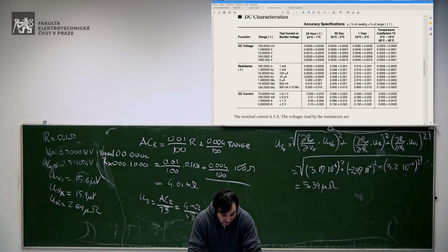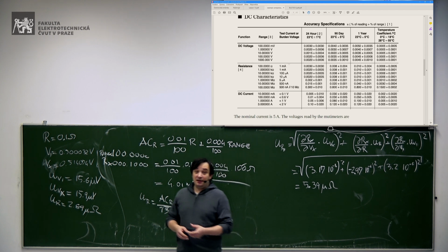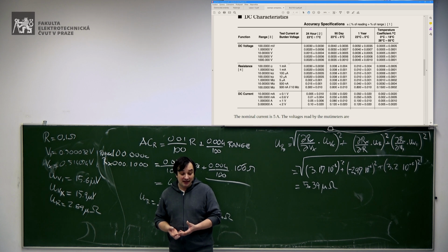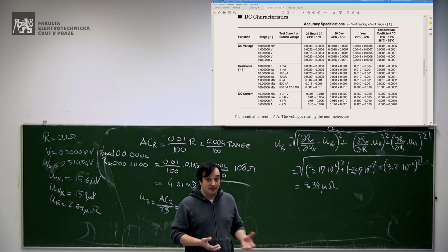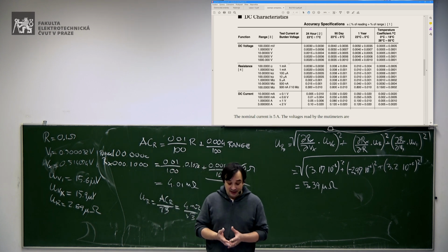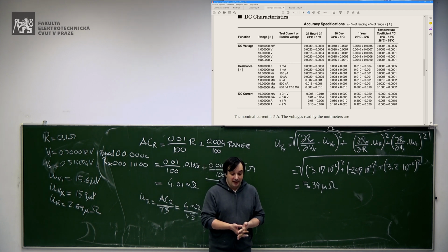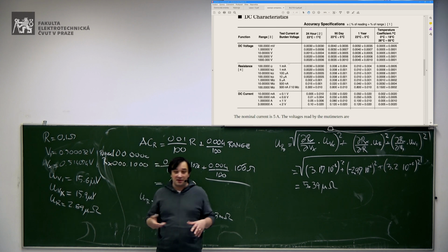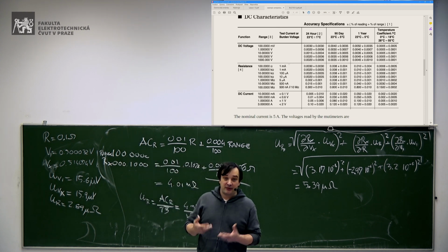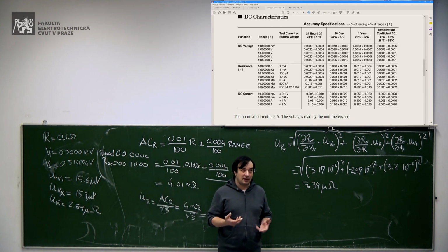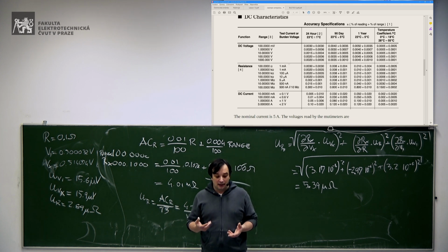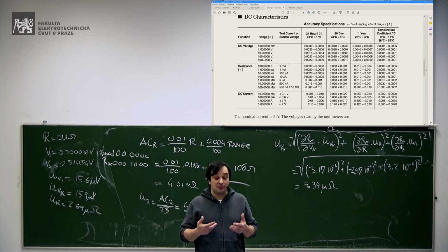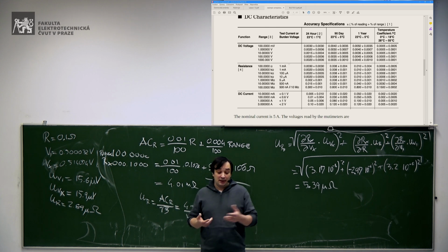Here you have basically only 1 milliampere with this method, which means that you have the same resistance, but 1 milliamp means that the voltage is about 100 microvolts. Think about that. So you have 1 milliamp over a resistance which is about 0.1 ohms. It means that you have about 100 microvolts, okay, correct? Yes. So you're measuring a voltage which is 100 microvolts.